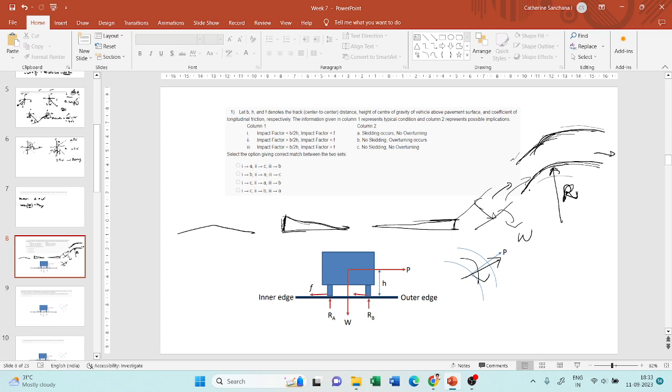Okay, you will increase the width of the road on a horizontal curve, which you will call extra widening. It will be denoted as WE. On a curve you should remember that you will provide something called super elevation on a road in the cross sectional direction, and also you will be providing an extra width for the lanes.